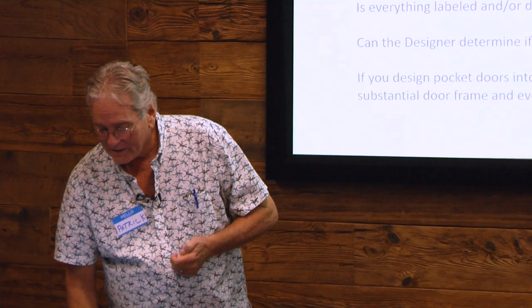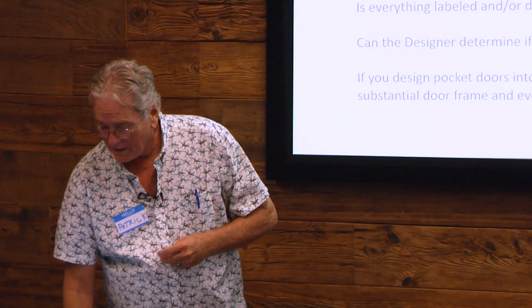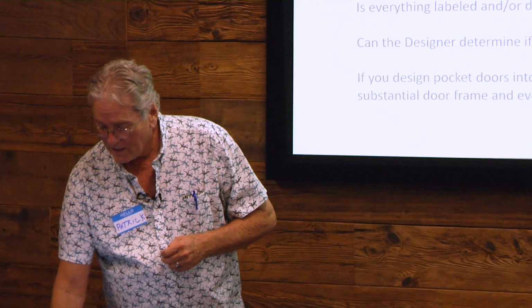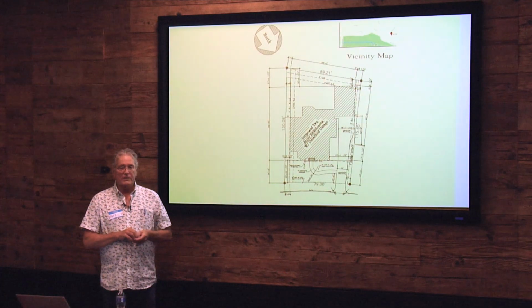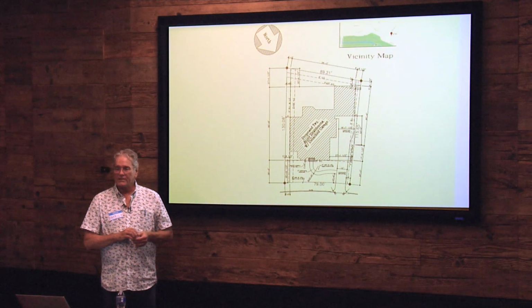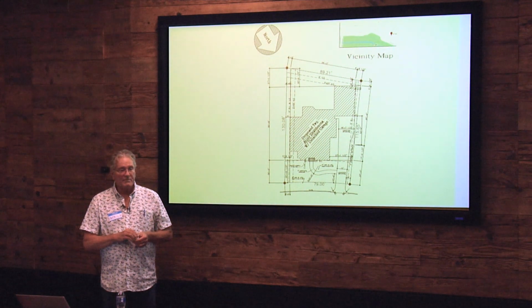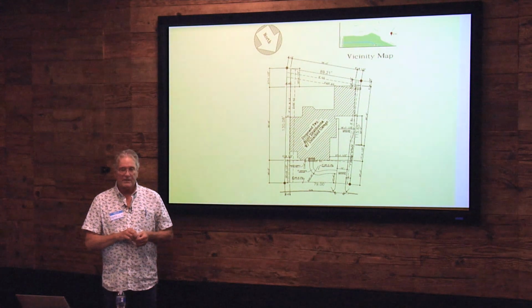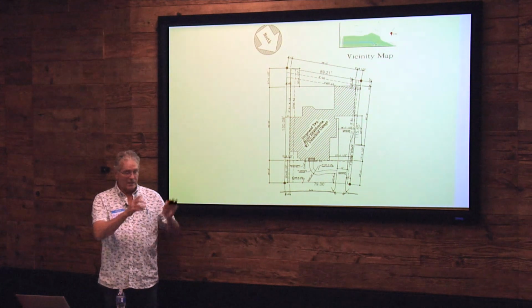Let's see if I have any things on here. At door sizes, look at cladding. In general, I say that the more things that are noted on the plan, the better the project's going to go. Not everything's going to be labeled. There are some designers that label floor coverings, other designers that don't. So you'll see carpet, tile, wood, but some don't. My opinion is they really should, so ask them to do it.